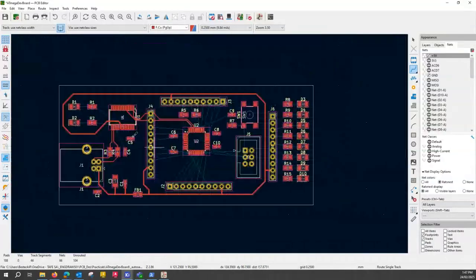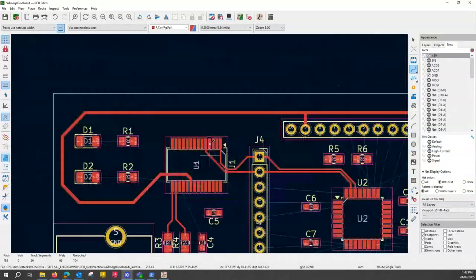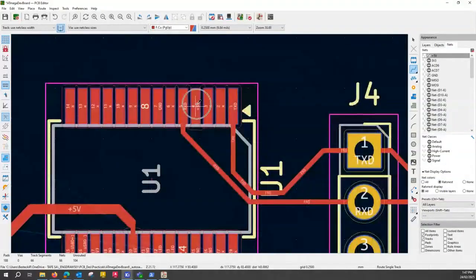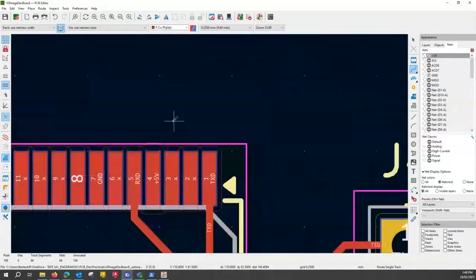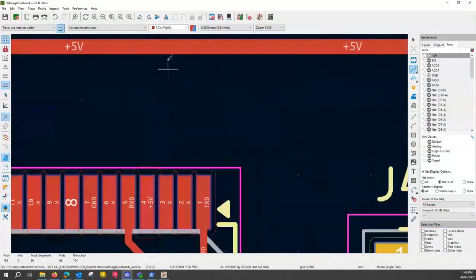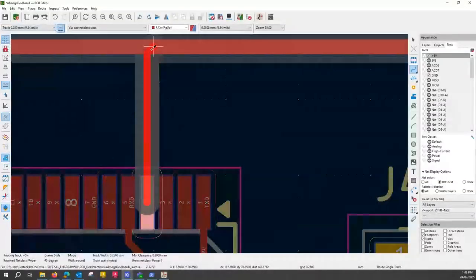We still need to supply power here to our FTDI chip. There's a second 5 volt input there. So what I'll do is I'll just run, this one can be thin actually. It's not a big distance, so you could easily just use 0.25. But what we could do is, yeah, that's what I'll do. I'll just change to 0.25 and just go from here, just connect there, done.